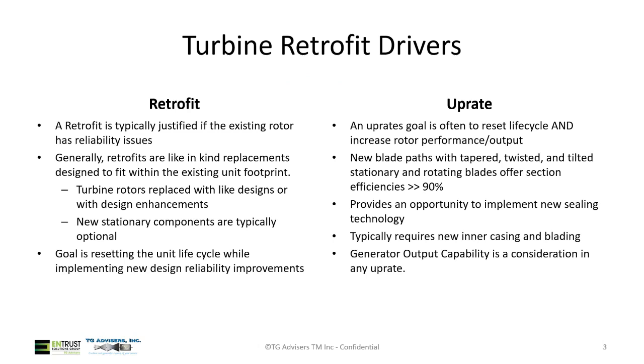So for the turbine side of things, retrofit drivers. When we talk about retrofits, and really uprates are retrofits too, the retrofit goal is typically to take an existing rotor that has some kind of reliability issue, some kind of concern, be it SCC or other things, and produce a new rotor that will meet the life expectations and reset the unit life cycle. The basic retrofit would be a turbine rotor like design, or maybe some design enhancements to improve reliability. Sometimes stationary components are optional.